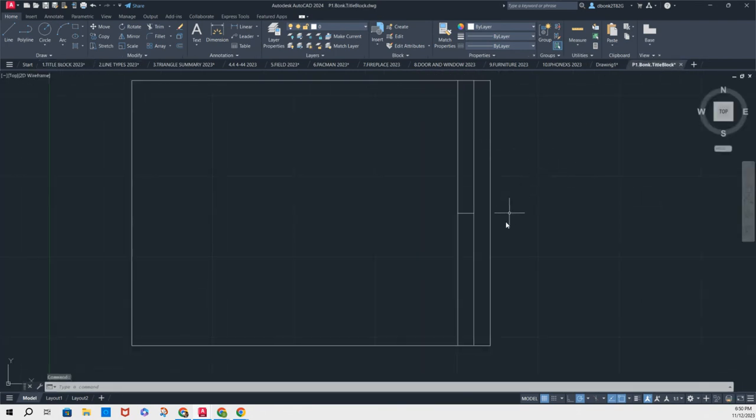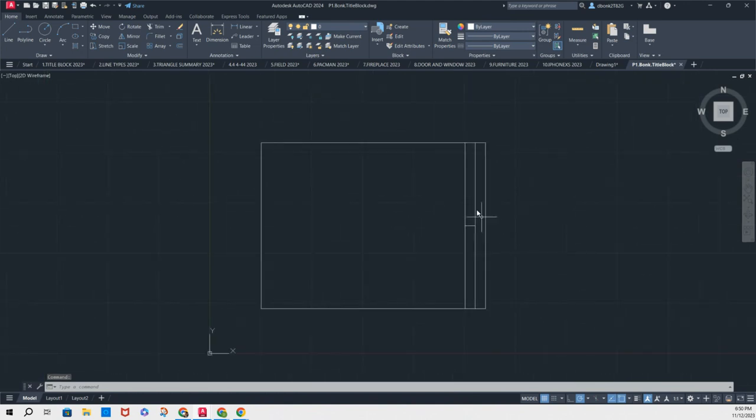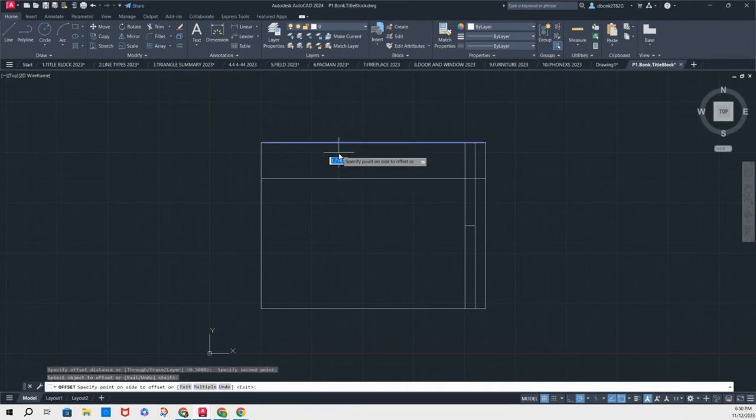All the way out here with a new one. What we're going to do is use these horizontal side lines to make offsets and put lines here where we need them, and then we're going to get rid of what we don't need. So watch this. It's going to be click the offset, click this. Again, you have to click it 3 times to get the first offset started when you're starting this command.